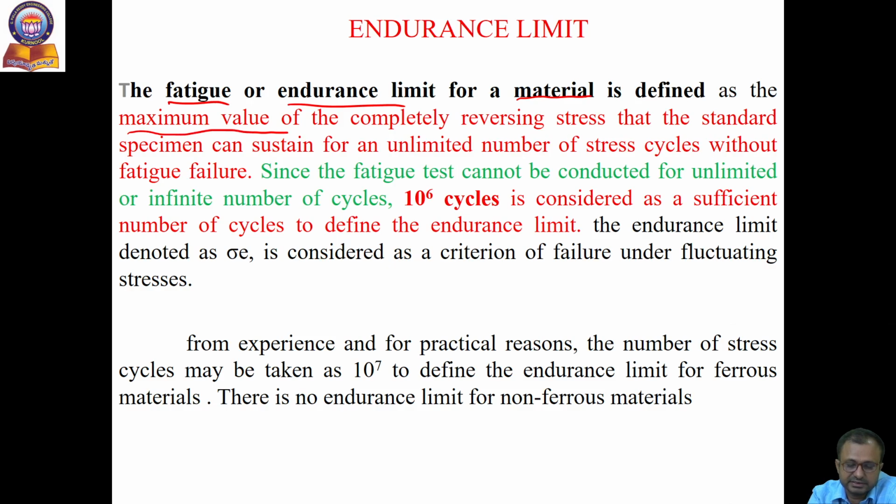Here we define the endurance limit as the maximum value of completely reversing stress cycle that the standard specimen can sustain for an unlimited number of stress cycles without fatigue failure. That is nothing but the endurance limit.